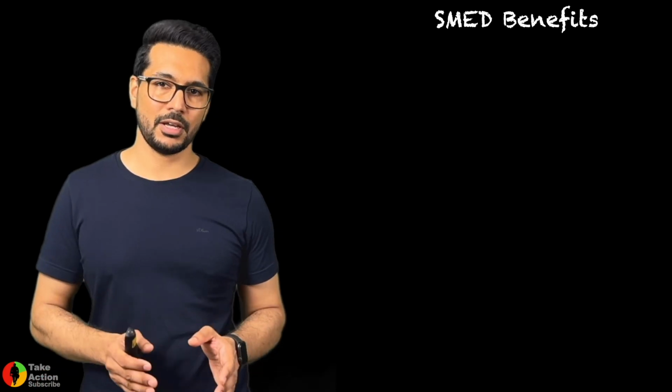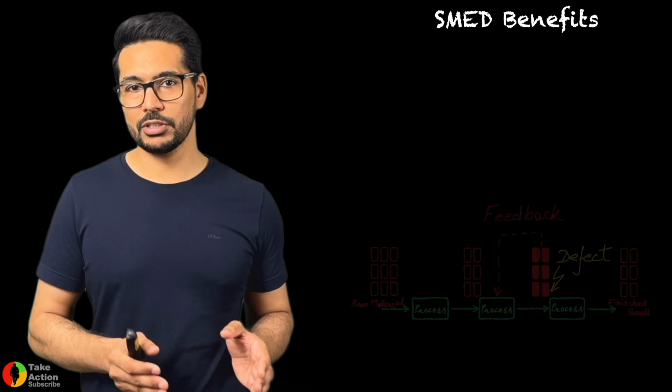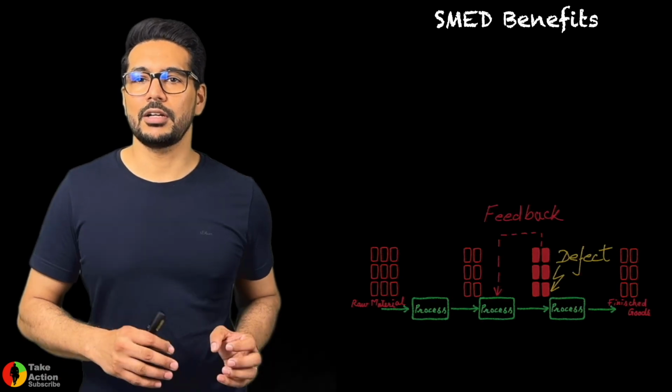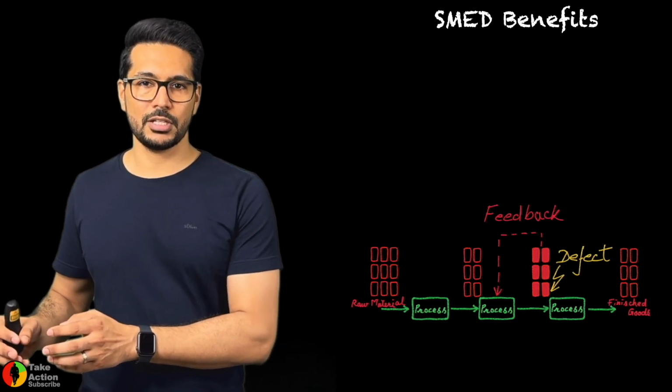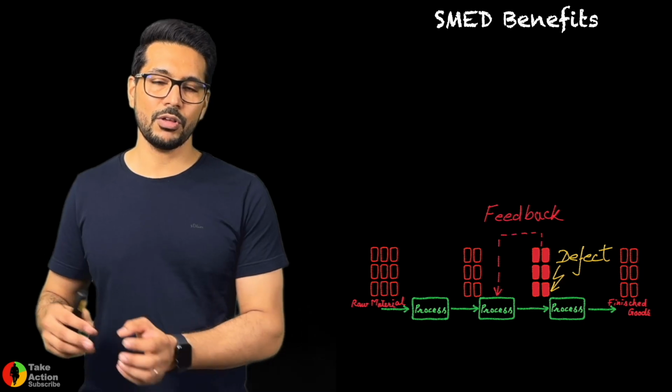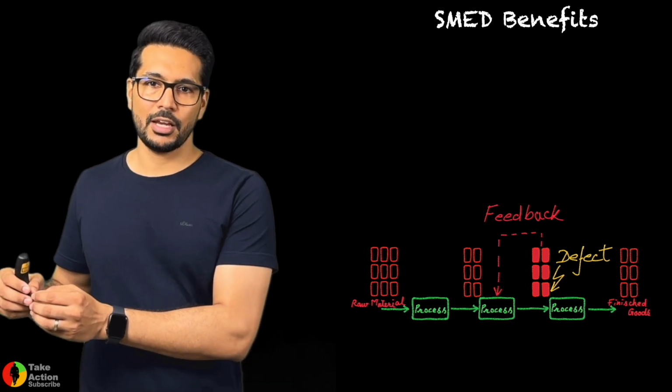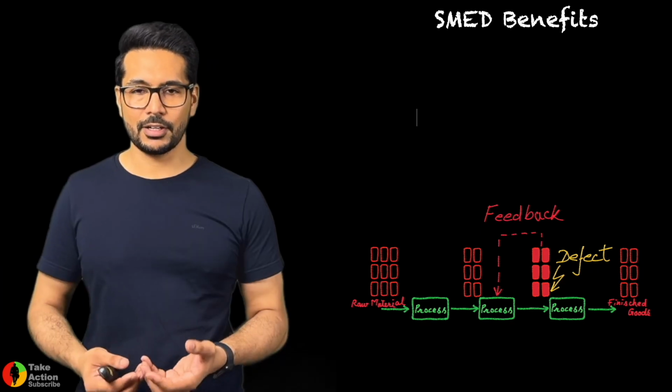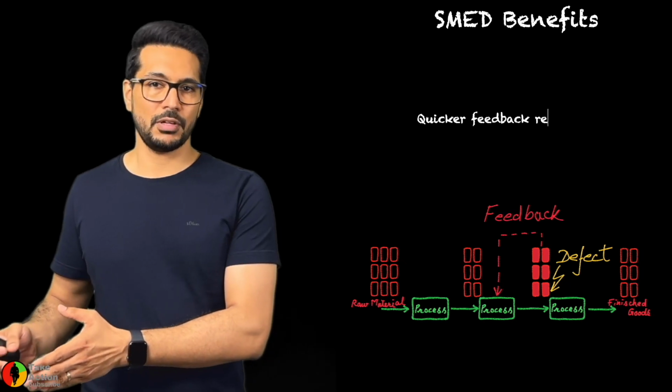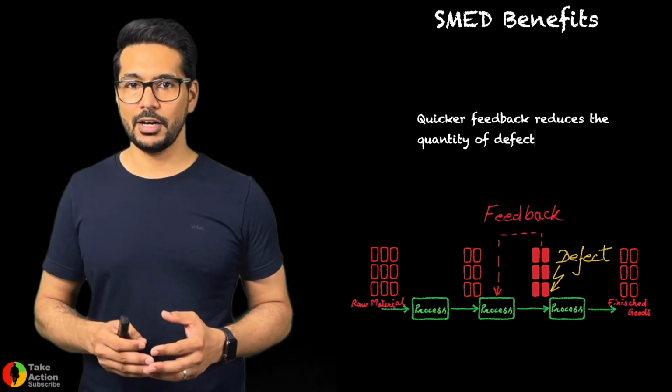Now with the setup time reduction, if we reduce the lot size to 50% and we are sending to our customer process in much smaller sizes, now if the customer process detects any defect in the part, definitely the maximum affected parts will be 50 and not 100.